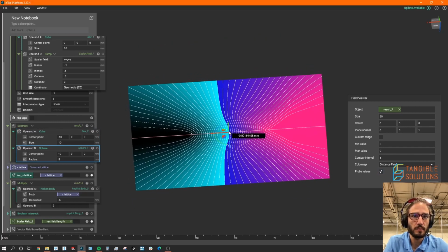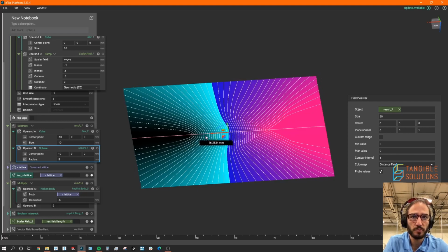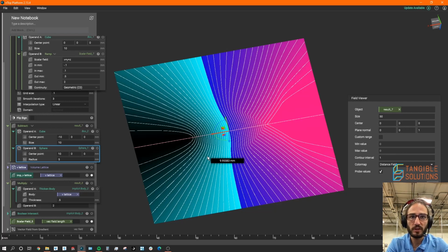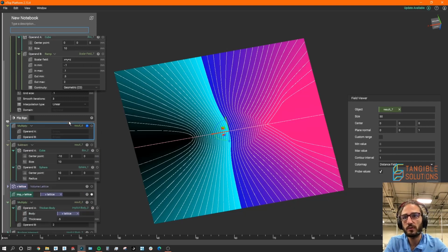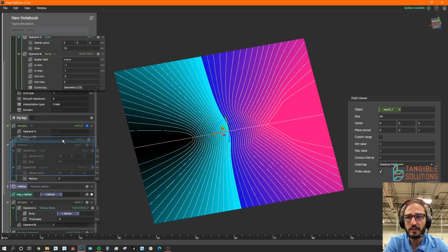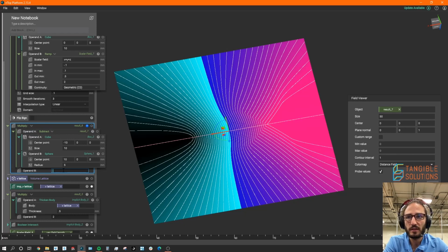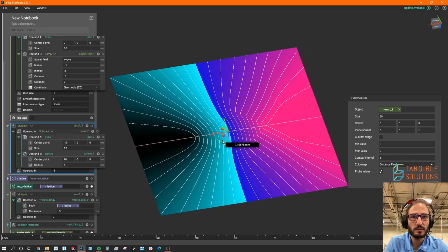a positive side and a negative side, and essentially exactly where these fields are intersecting and colliding is this really cool zero plane. So from a surface standpoint, you can use this to pull surfaces in nTopology and use those surfaces to define this distance field of a positive to a negative. And again, what we've shown here that's really cool is understanding where your gradient is in space, because I can take this particular gradient and multiply it by values,